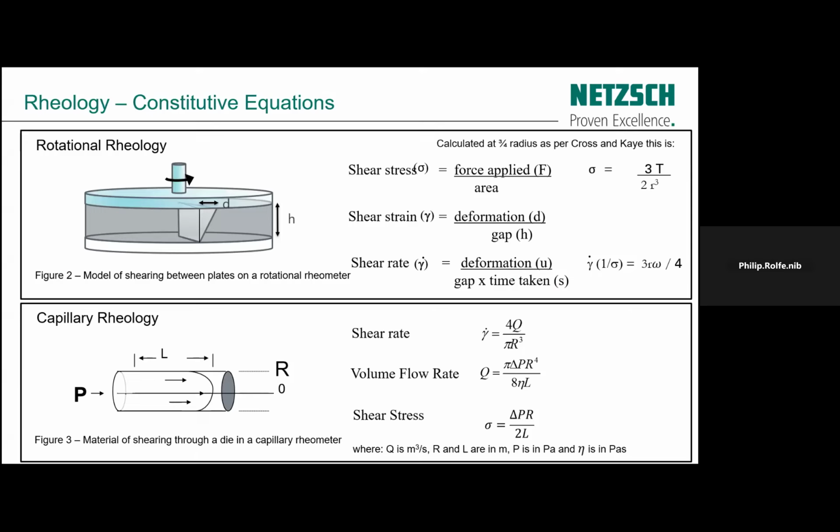So you could say, well, how do we actually correlate what's going on in the spray nozzle to what's going on in the rheometer? And it's a matter of shear rate calculation. So if you're going through an orifice, use Poiseuille's law to calculate the true shear rate. This is the same formula that we use in capillary rheology.